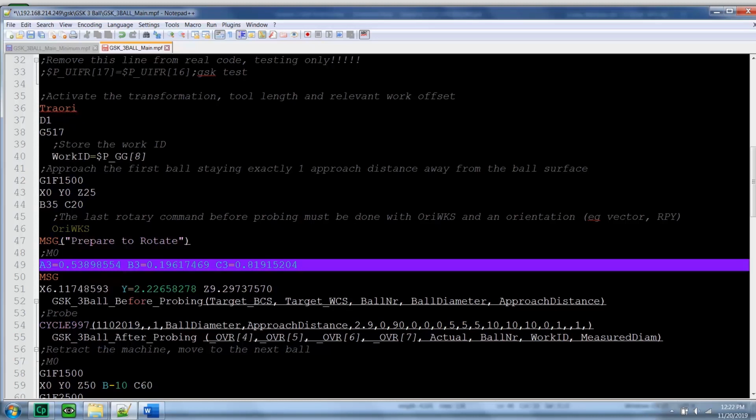If you can go to 10 or 12, that's even better because then that pushes all the errors out into ranges that are just completely and totally impractical for all machining. Even though 8 decimals in metric is far beyond what we could actually get out of a machine, it does make the math work better and prevents rounding error from creeping up into numbers that you do care about.